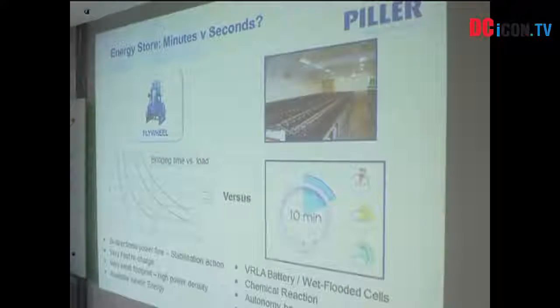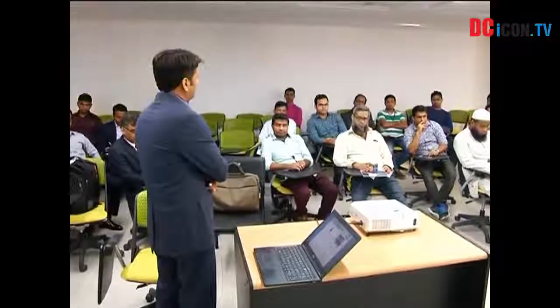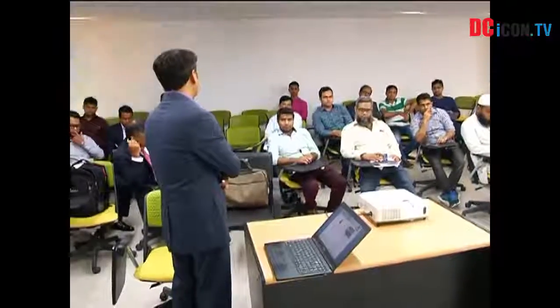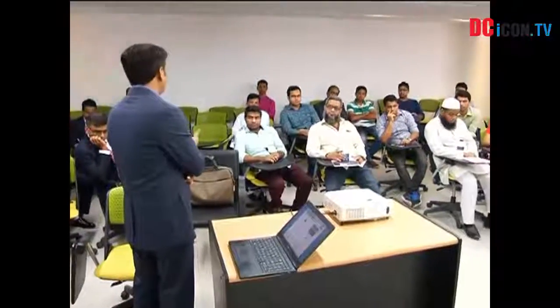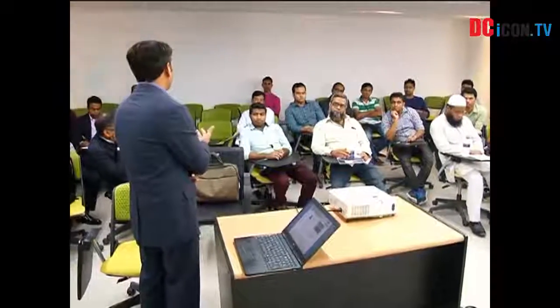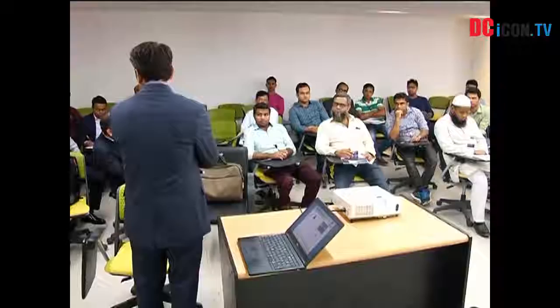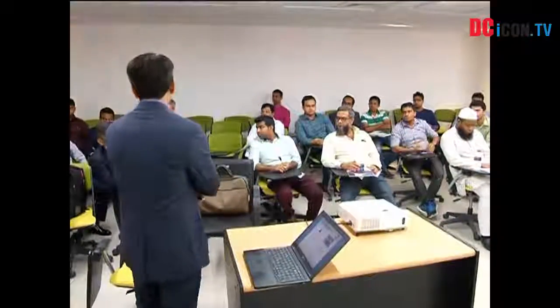Noise and vibration: because there is a flywheel and other parts, we could show you the size. You typically will not know that there is a flywheel. In terms of noise and vibration, you really cannot make it out. The only applications we know are some special semiconductor plants where they need a certain vibration level. We have a lot of installations, but noise is also comparable. A 1000 kVA rotary UPS is 77 dBA at 1 meter, and a static UPS would be in the same range, maybe 80 dBA or something in that range. So it's quite silent.